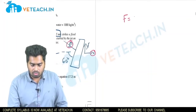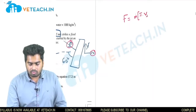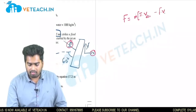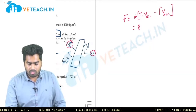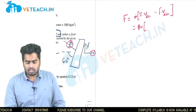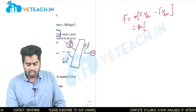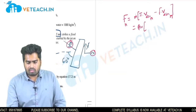Force F is equal to m dot into initial velocity in the direction minus final velocity in the direction, right? So this is rho a v. So if you know velocity, in this sum in which direction is he asking to find the velocity? He is asking to find the velocity in normal direction, so I have to write n here. Okay, so what is the velocity in normal direction?